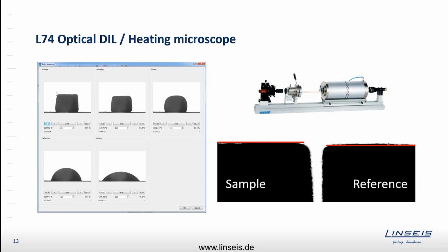In that case, you just look at the very close upper edge of the sample in just some millimeter broad image view. As you see on the right picture, usually you have a sample next to a reference body. The reference body comes with the system, is provided from us to correct the expansion factor because of the atmospheric changes in there. And the system then automatically recognizes the shape or the border between sample and background.